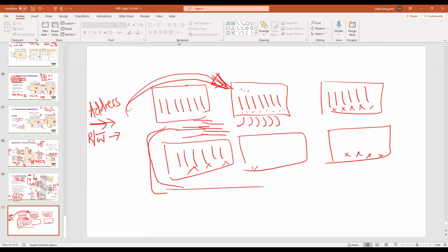Now, this information will usually go out in parallel. It will go on the bus, each bit on a specific line, and it will go to wherever it's going. Or if you are writing, you will provide your 8 bits on the bus so that they can be shifted into memory. So it might be series in the sense that you have disabled everything else and you're looking at one register, but it is also parallel in the sense that either you're parallel loading or you're reading the information, but in parallel simultaneously.